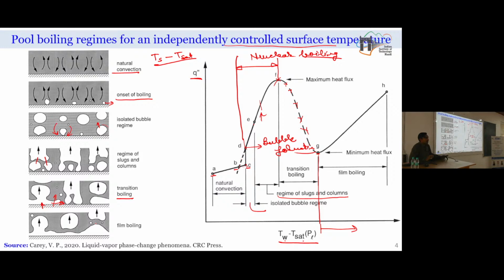Yes, but typically whenever we are in this particular regime, the isolated bubble regime, what will be happening? We will be having nucleation of the vapor and a small vapor volume will be generated, but if surface forces are significantly large in comparison to the buoyancy forces, that bubble cannot leave the surface. Slowly it will be growing in size, and once buoyancy is dominating, then it will be leaving the surface.